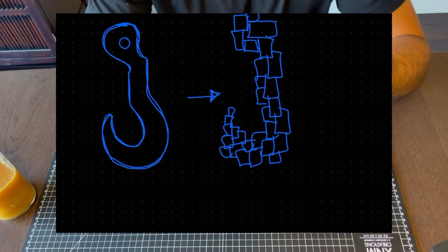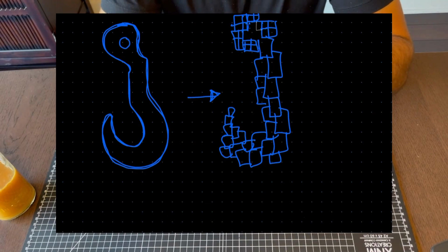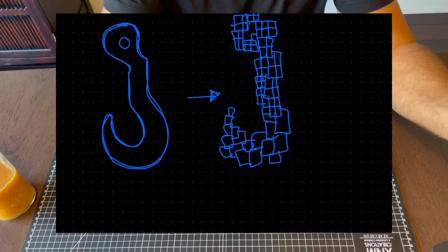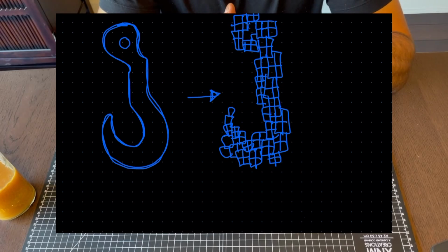And when it's connected to another block, we measure how strong or how much force each connection from one block to the other is put under. If you want, you can make these blocks smaller. What that does is, let's say for example, we have a hole like the one on the top here. If the block is too big to represent what that hole does, making the block smaller means that all the very tiny features that make up this part are now represented more accurately.